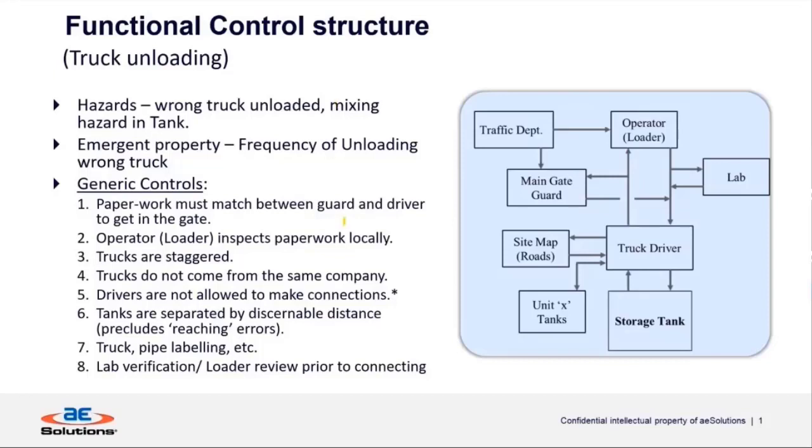And this one was interesting because the weakness found here was, as you can see, drivers are not allowed to make connections. This one right here. But there was one unit buried in this very large site where the drivers did everything. They made connections and they unloaded, and it was one of the chemicals that was going to be involved in this inadvertent mixing scenario. And so it wasn't a far stretch to imagine potentially this driver coming in, expecting to make connections and unload, and getting to the wrong tank.